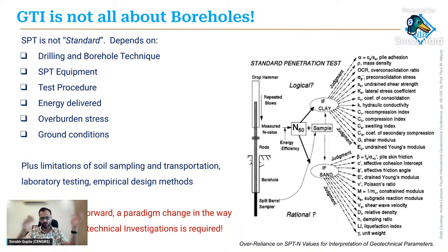GTI is not only about boreholes. If you really look at why, there are a lot of limitations to borehole-based investigations. First of all, the gold standard of investigation these days, or still unfortunately, is SPT, the standard penetration test. So we always like to educate our customers that there is nothing standard about the SPT.